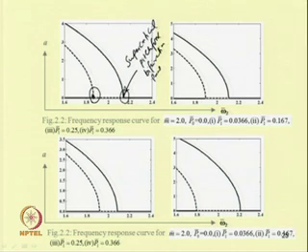While sweeping the frequency, at the subcritical pitchfork bifurcation point the system will be subjected to a jump up phenomenon, because only the stable branch is available in the non-trivial state. The system then follows this non-trivial branch till it reaches the trivial state, and after that the system has a single state solution.